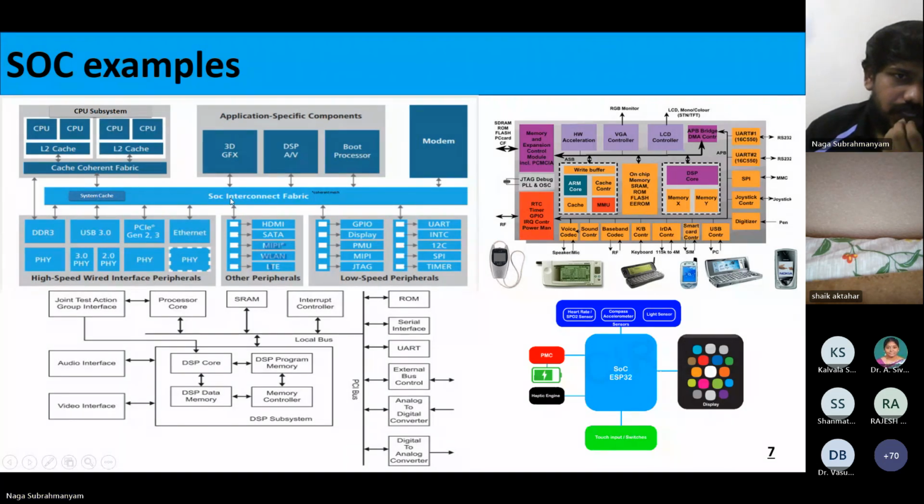Inside this NOC, there are so many routing algorithms. It's all our digital logic only. From here it will route the data through this NOC and it will use any one of them, or it will consume data from any one of them. And it has its own cache memory. Nowadays these NOCs are very, very powerful. Those NOCs are themselves big systems. Sorry, I used a word called NOC. NOC means network on chip.